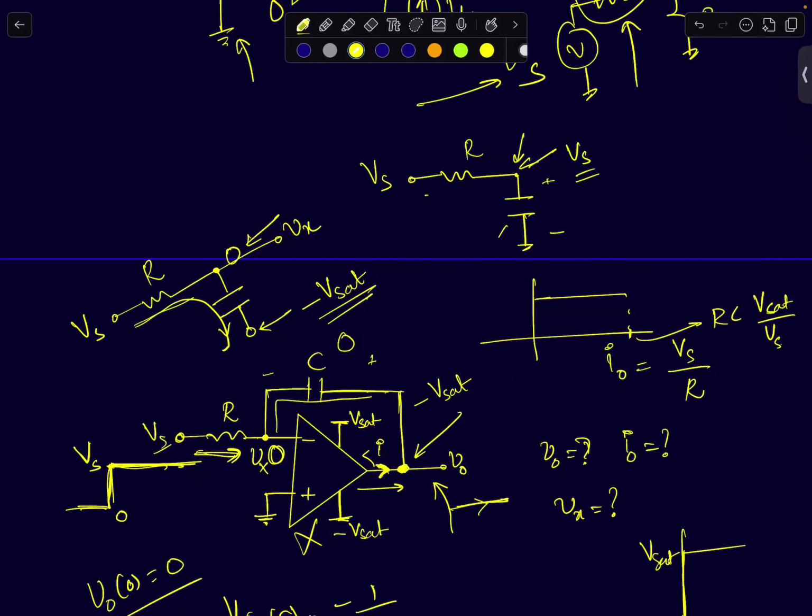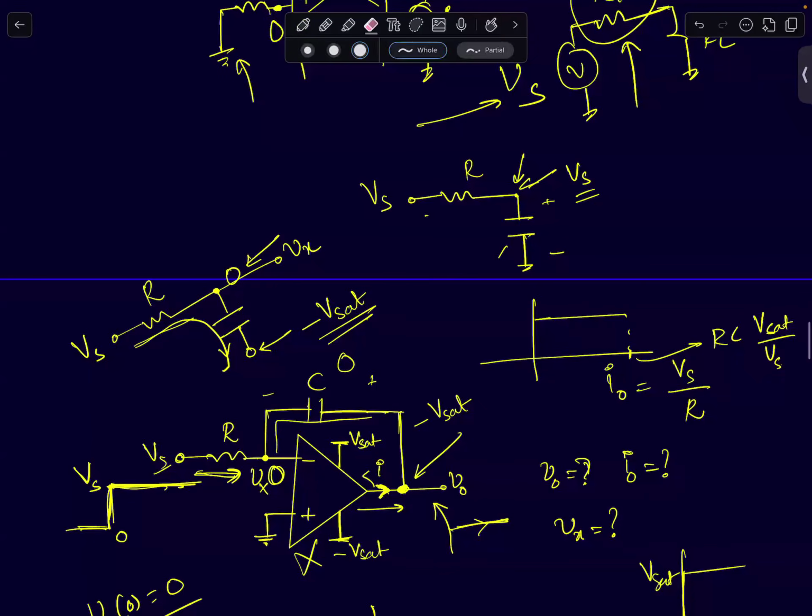Yes. So a capacitor will undergo this charging. Whenever you have a first order resistor and capacitor, as far as this R and C are concerned, suddenly it will look like I have applied an input Vs. Now the opamp is no longer in the circuit. This will look like an RC circuit with a step input of value Vs. And you can treat the capacitor as initially charged to a voltage of minus Vsat.